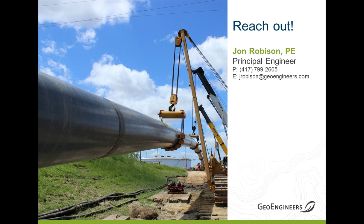Planned entries are, we're going to go in 200 feet when the pipe's 200 feet in the ground, and we're going to do a check survey to recalibrate all of our location control systems in our pipe. So that's a planned thing. And then depending on how tight the tolerance is, we're going to go in every 1,000 feet or 500 feet or 2,000 feet, again depending on how tight those tolerances are, to recheck the position of the MTBM, recalibrate the location systems, and verify for ourselves that we're in the right place.